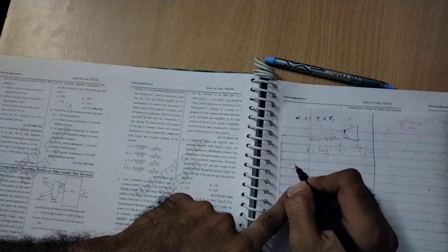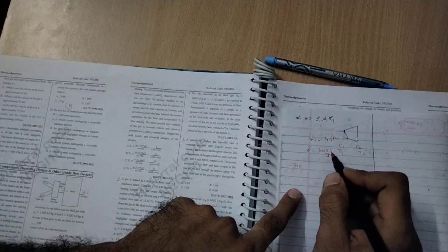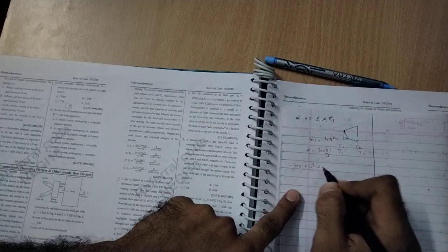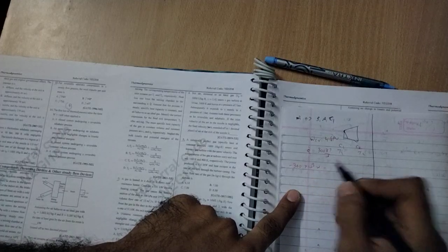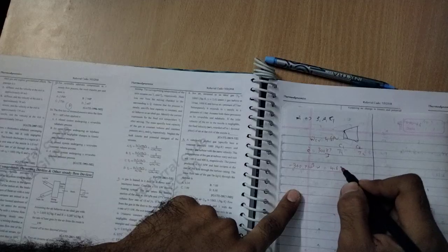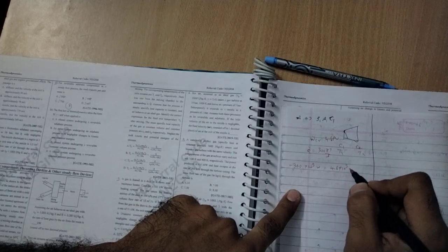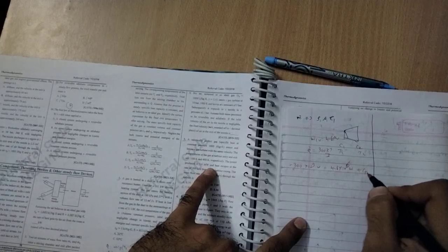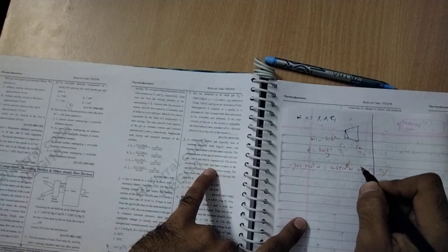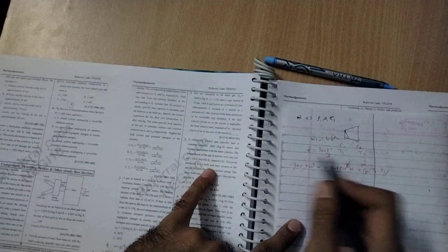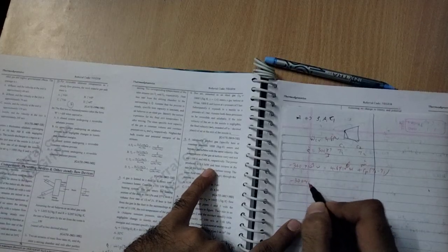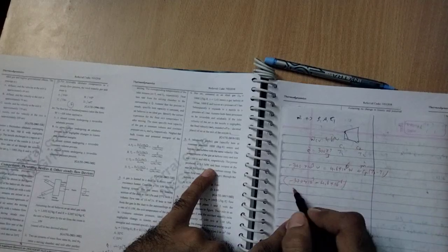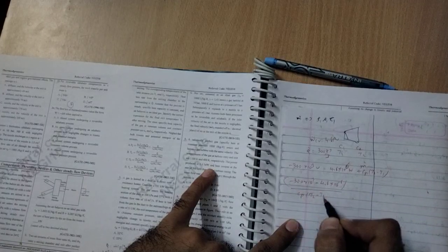So minus 300 times 10 power 3 joule per second equals work produced, plus 4.6 times 10 power 6 watt plus m dot Cp (T2 minus T1). So minus 300 times 10 power 3, heat is lost, minus 4.6 times 10 power 6, divided by Cp (T2 minus T1), equal to m dot.